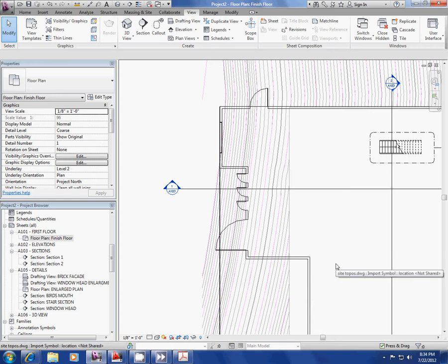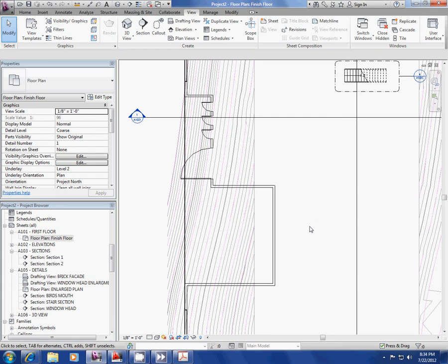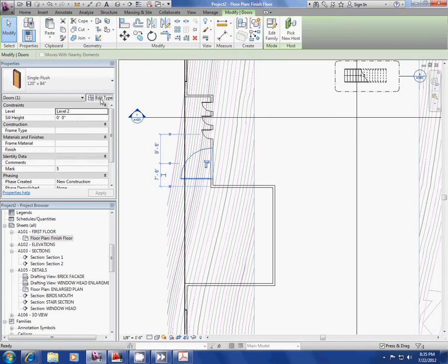Certain partitions have those parameters, like bathroom partitions and things like that. They come with embedded parameters. You could also add parameters. So say you want the door frame to widen, but the door itself to stay the same. That's all a matter of editing the family itself, but this is something that's already embedded with the family type.